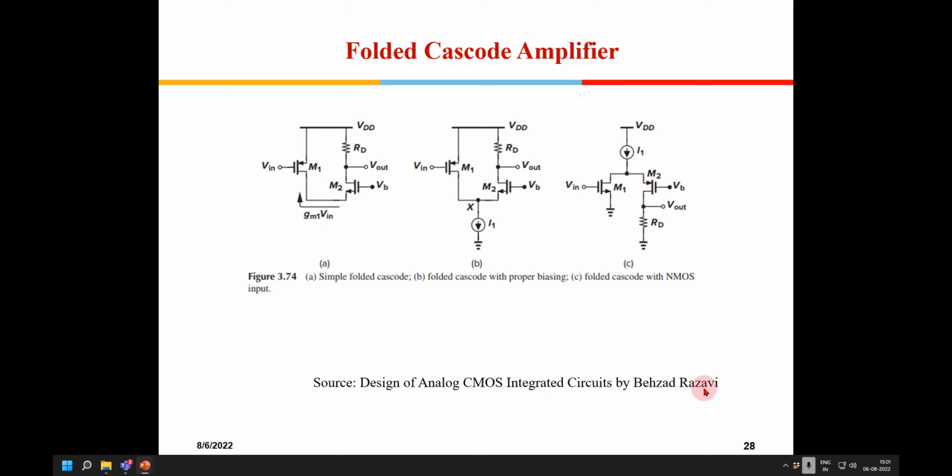So this is there in your textbook. So everywhere the gain will be the same. The only thing is the way the PMOS is connected, you can have different configurations. All of them, if you see properly, you can spend some 15 minutes on these circuits, including the derivations if it is there. It is a common source amplifier followed by a common gate amplifier.